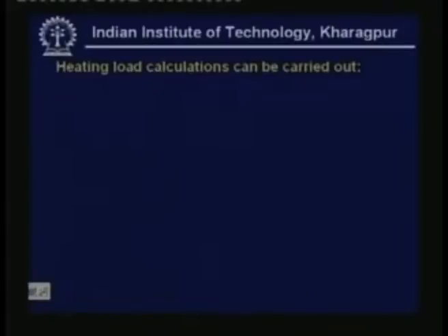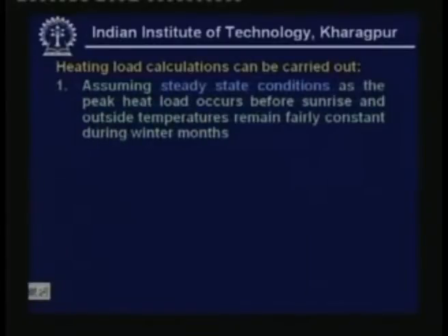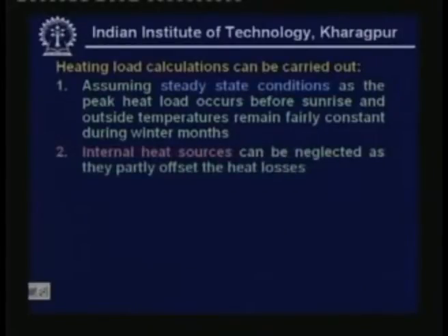Heating load calculations can be carried out assuming steady state conditions, as the peak heat load occurs before sunrise and outside temperatures remain fairly constant during winter months. And also you can neglect internal heat sources while estimating the heating loads, because these internal heat sources partly offset the heat losses.